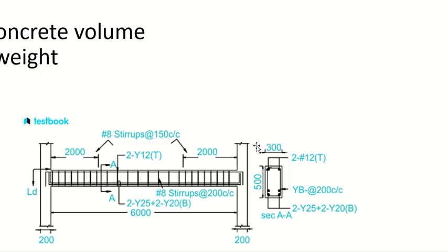Now see, it is now interesting. See now, what is happening? Two spacings. Okay. Whenever these things come up, I need to explain it to you. Stirrups near the supports are closer. Stirrups in the middle have more spacing.